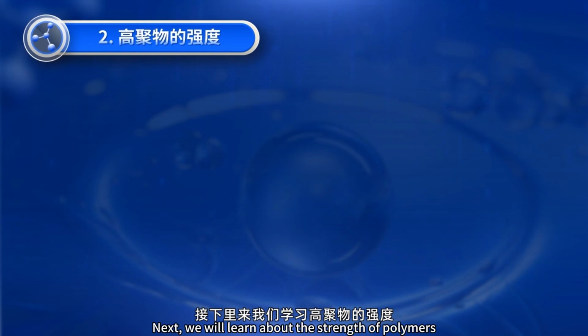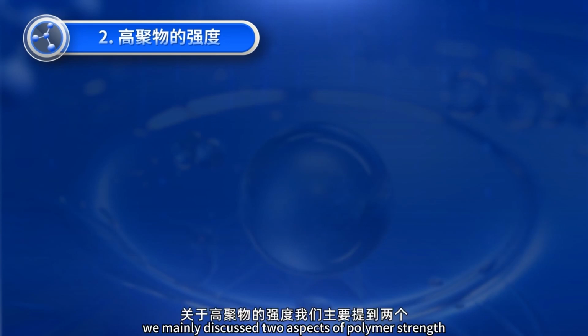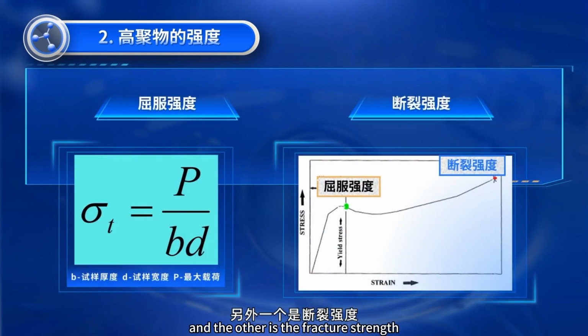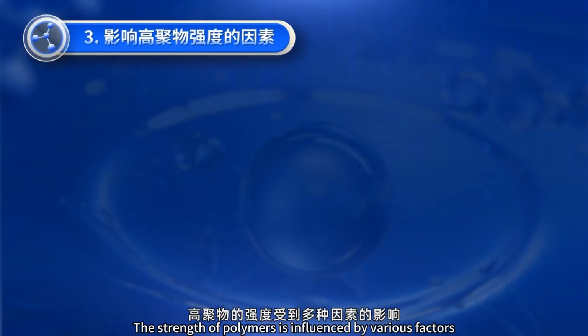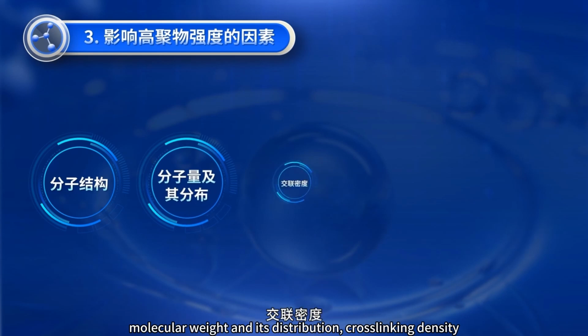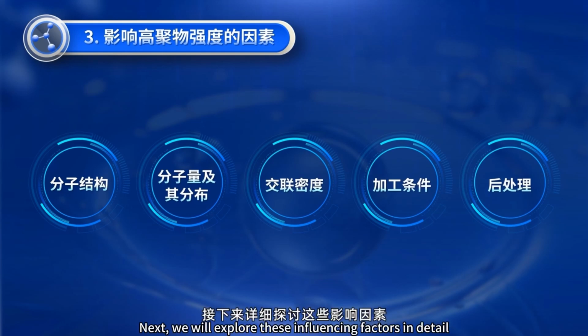Next, we will learn about the strength of polymers. Based on the previous course introduction, we mainly discussed two aspects of polymer strength. One is the yield strength, and the other is the fracture strength. We will not go into detail about their calculation. The strength of polymers is influenced by various factors. These factors include molecular structure, molecular weight and its distribution, cross-linking density, processing conditions, and post-processing. Next, we will explore these influencing factors in detail.